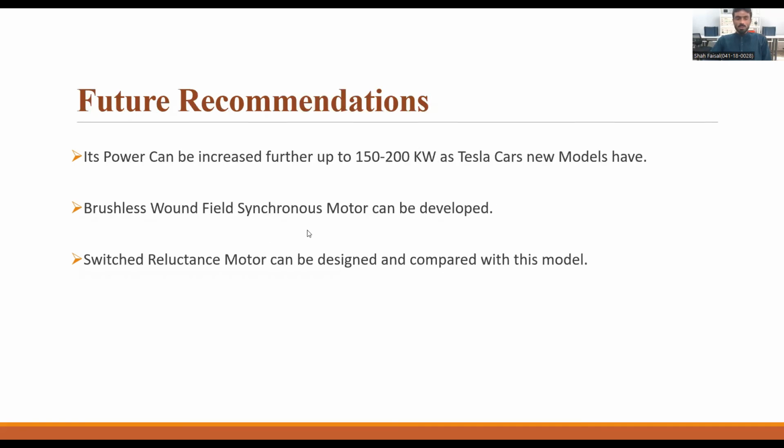Future recommendations: its power can be increased further up to 150 or 200 kilowatt, as the new Tesla car models have. The second is that a brushless wound field synchronous motor can be developed, and a switched reluctance motor can be designed and compared with this model.